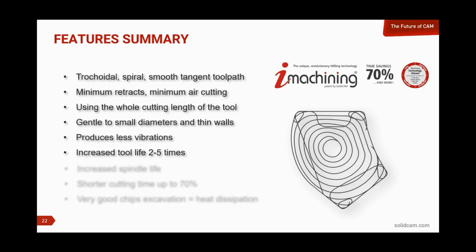I've got a video I'm going to show you in a moment that really shows how high a performance we can do, and yet we get significantly longer tool life. Because of all the reduced vibration, because of the reduction in the linear force vectors against the machine, a nice added benefit is that we're also increasing the spindle life because we're not creating vibrations on the bearings, we're not forcing loads on the ways, we're just treating the machine very nice.